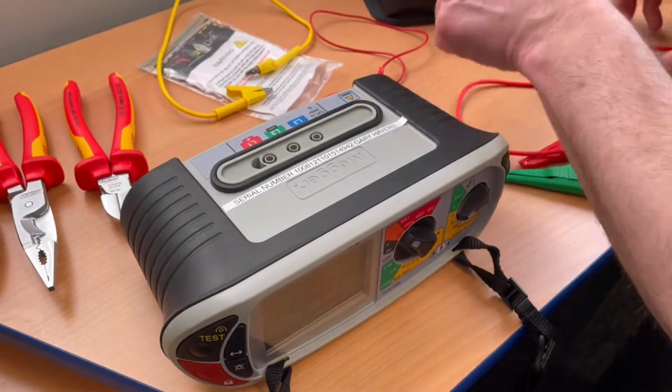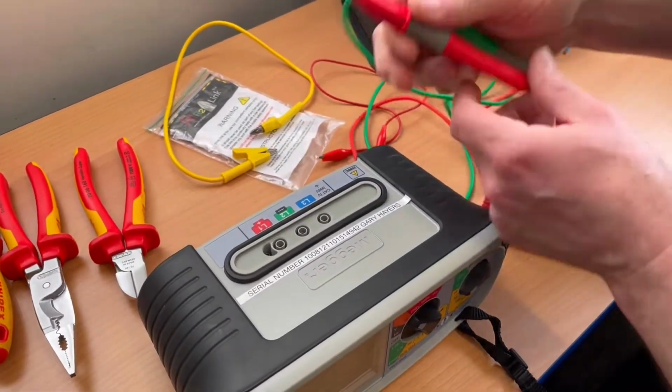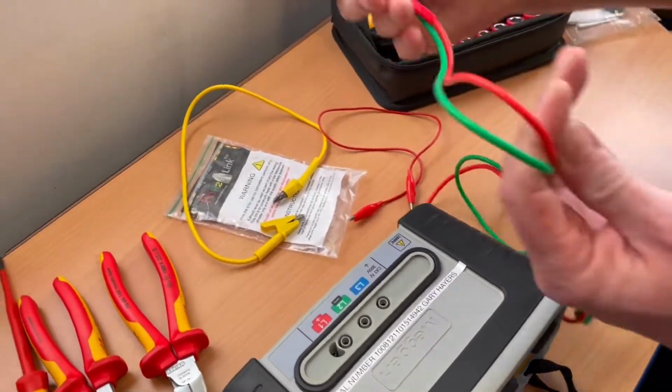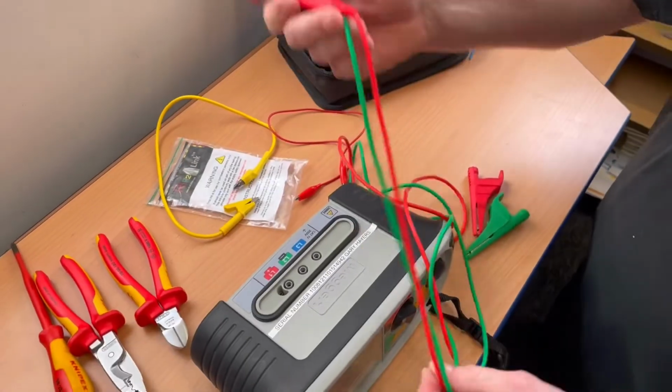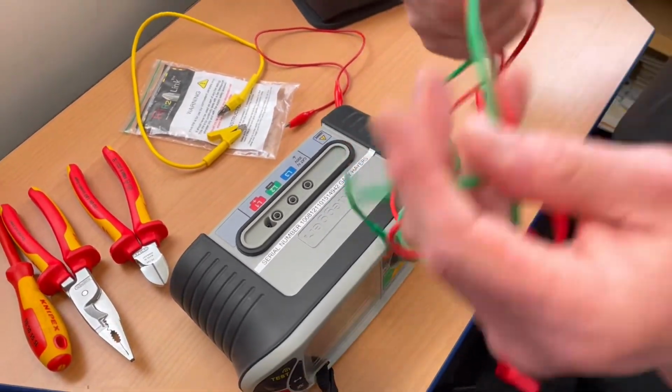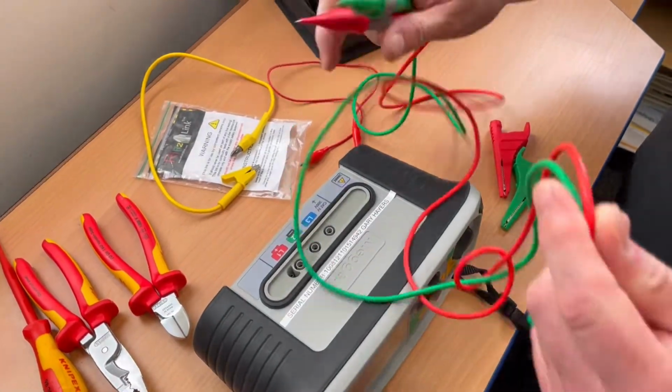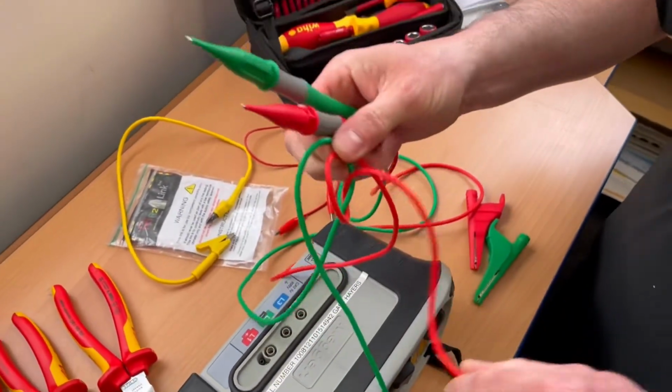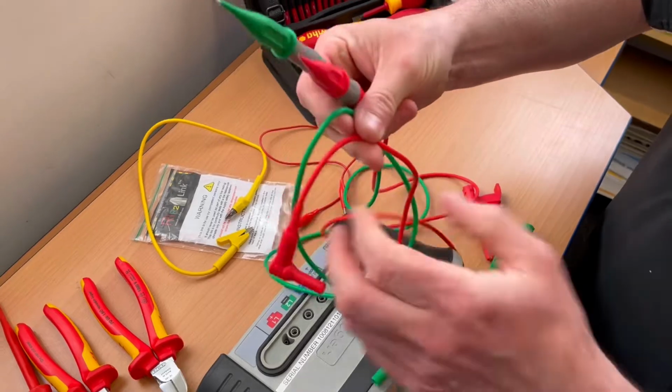So our machine's on and working. We've got our leads. Again, we need to do a bit of a visual inspection of these before we use them. So just have a little once over, check there's no nicks or damage in them, as you get those leads out of your box. And that's really important in a college setting, that you have a good once over on those leads, even though it is a dead test. If they've damaged the leads, obviously it's going to cause a problem with the results.